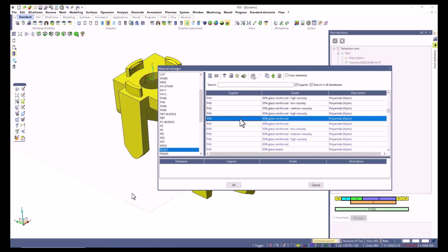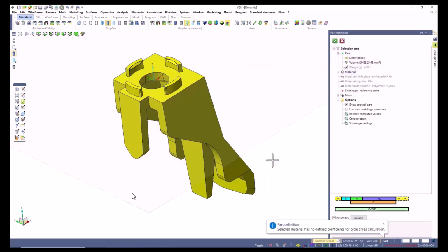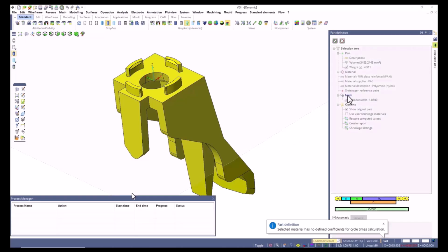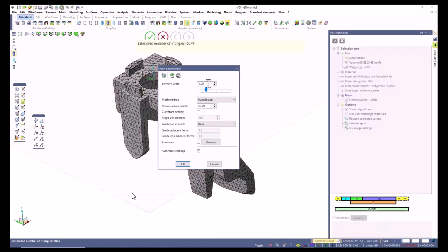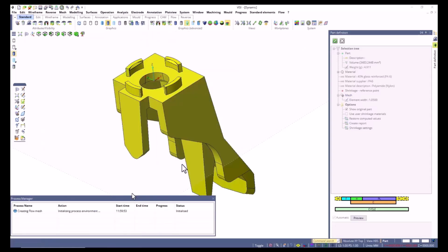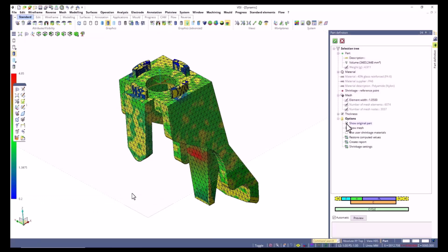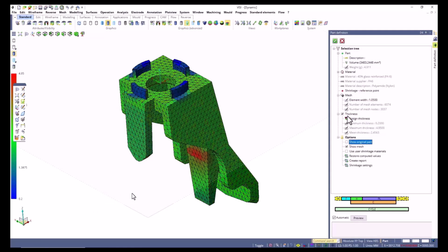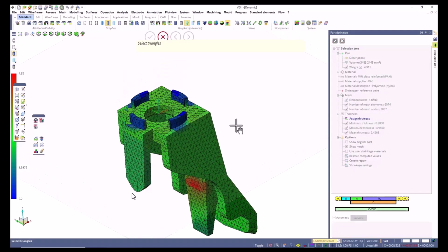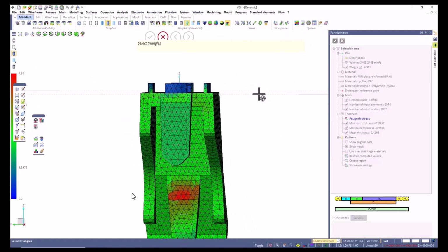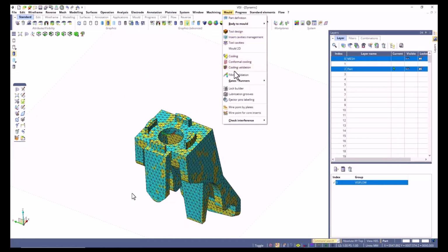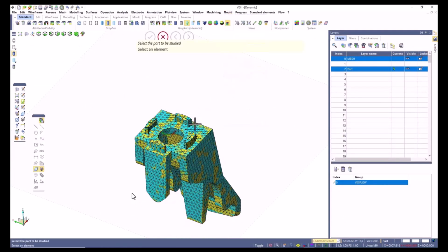Choose whatever material that we're going to choose from. So we're talking about thousands of materials in here. And you can see here's that mesh variable right here. So you can change your mesh properties, generate the mesh basically from there, and change your mesh properties. So this was available previously when you used flow light. Now it is in the part definition. So once this is completed, you will now be taken right to the filling validations module as well. So we can assign thicknesses in here. You can basically change your different properties for this as well. So once confirmed, go into filling validations, select that mesh.